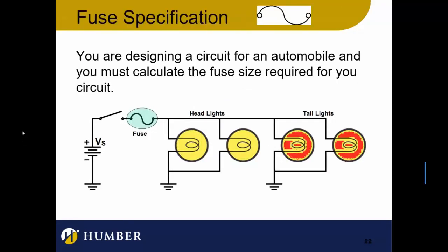Okay, good. So now let's say you're designing a circuit for an automobile and you must calculate the fuse required for the circuit. By the way, this is on the exam. And there's a very good example of me doing it under the lecture material, and you will see that, it's there, and just watch that video. So what I'm saying here is that this fuse is protecting all of these lights. I have to calculate how much current all of these lights are drawing from the battery, and then I can select the right kind of fuse.